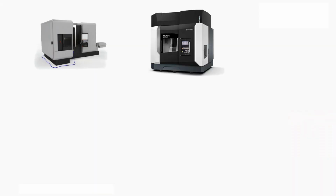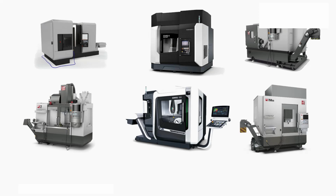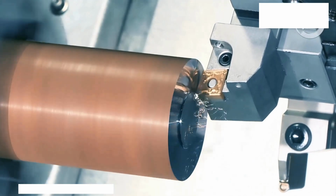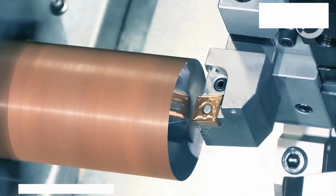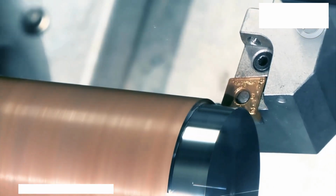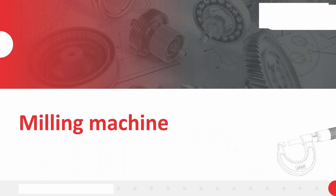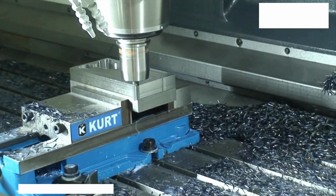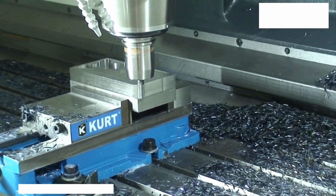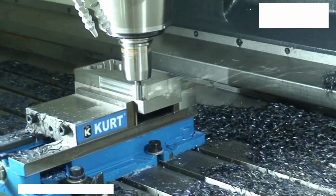The CNC technology is used in the different machining processes. Some of them are as follows. Turning machine. Turning utilizes a cutter that moves perpendicularly through the center plane of a rotating workpiece. The part shape depends on the shape of the tools and the operation performed to obtain the finished part. Milling machine. The milling process involves the use of a rotating cutter to remove material from a workpiece. The tool will be in the rotation, and the workpiece will be in linear motion.